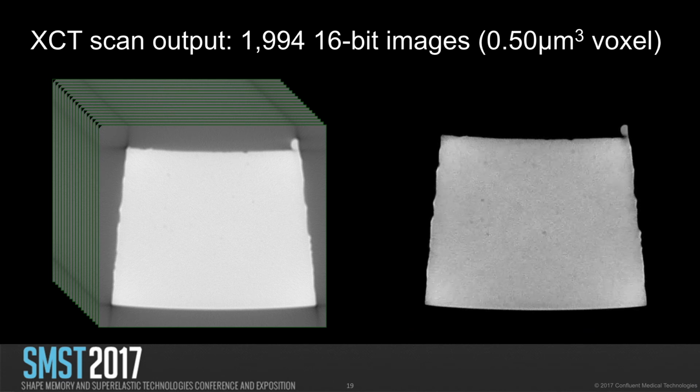You're looking at the cross section there of this strut, and the dark spots that you see are inclusions and/or voids. So we're definitely getting the contrast that we need to see the difference between matrix and inclusion. And what you're seeing on the right there is basically 50 or so of these 2,000 slices. We're just kind of indexing back and forth through them. So we know that we can see what we need to see. So that was pretty cool.